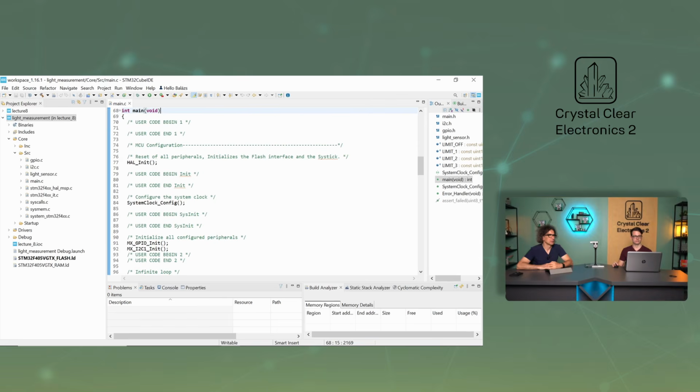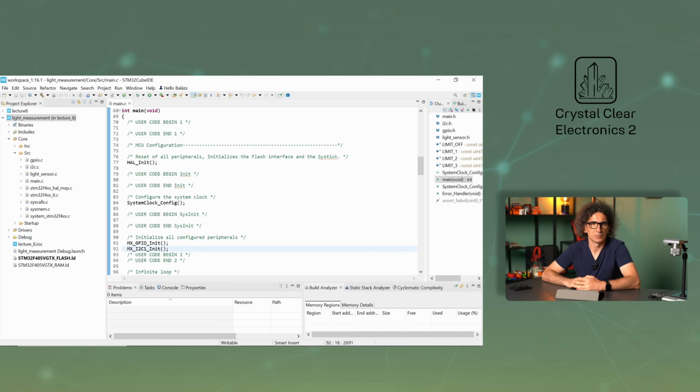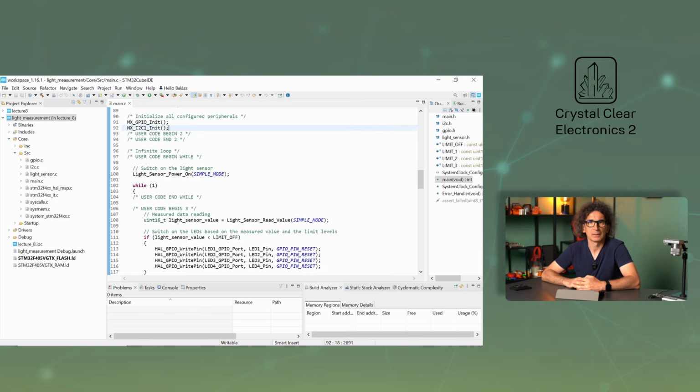We start with initialization, which is done for us by the code generator, but it's useful to know the processes. The generator calls the functions of the units, which starts with the HAL library, and then prepares the clock signals. After that, the peripherals take their turn, and the GPIO and the I2C are put in a ready-to-run state. From now on, it's our job to code.